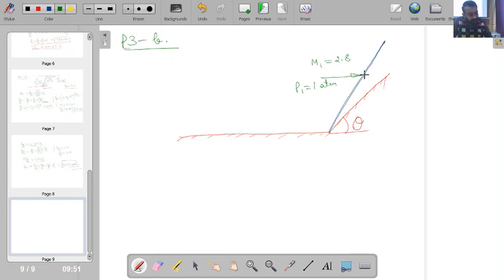Then I have here this as my M2, and this M2 is such that it is becoming identical to 1.45, whatever the downstream Mach number we were having in the previous part after passing through 2 shock waves. Is this point clear?